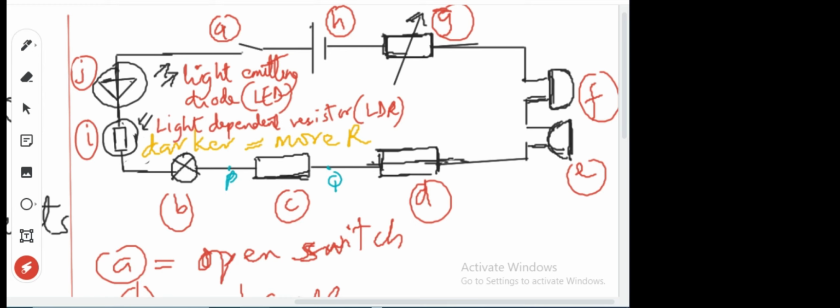But electromotive force is what you get when you add up all the potential differences in any given loop. In fact, there's a law we call Kirchhoff's law. I will read it later. Kirchhoff's second law says that in any given loop, like when you move around a cycle, from the positive side of the battery back to the negative side, all the potential differences will add up to give you the electromotive force. So the sum of all the potential differences is equal to the electromotive force.